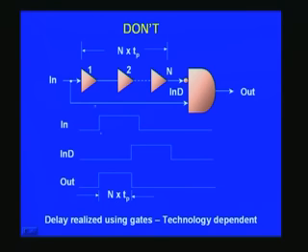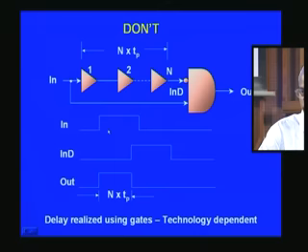So in which case, if you had not changed the design but you have changed the device, then what will happen? The time delay that you have put here will not be achieved in the current technology. So it will be tenfold less, which may not be enough to trigger some other mechanism that you might have envisaged at the point of designing. So that is to say that it is technology dependent.